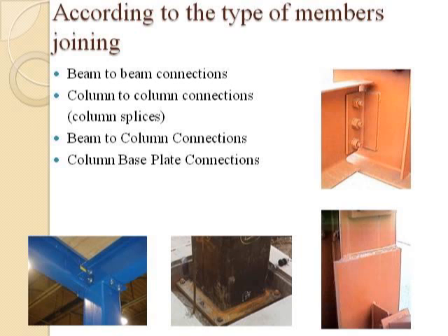Those connections will mostly be bolted, as we need to transfer the heavy loads the column carries to the foundation. So usually we'll go for bolted connection. We don't generally use welded connections for it. So those connections are column to base plate connections.